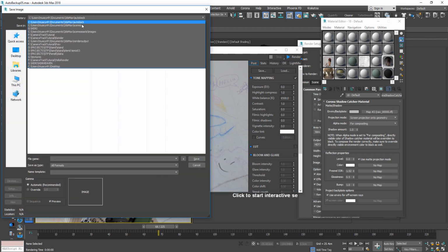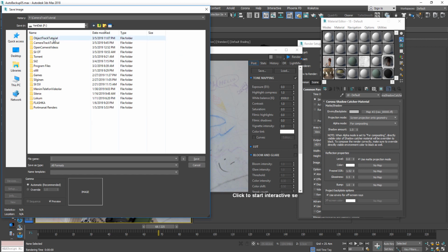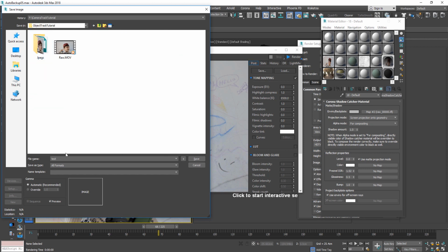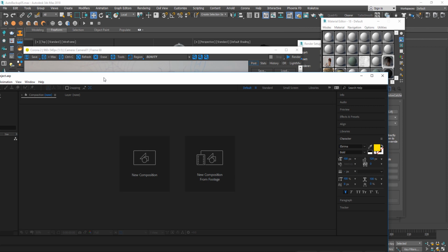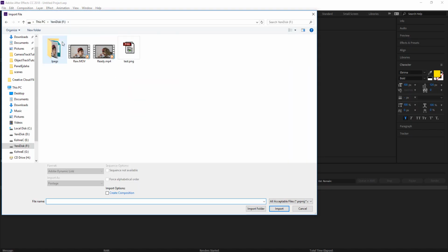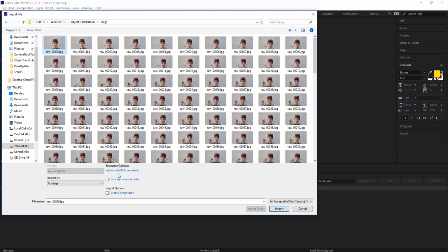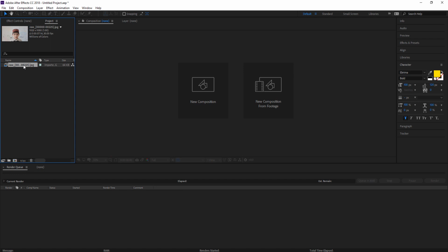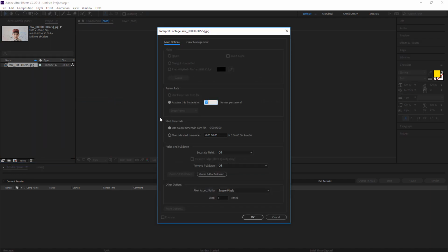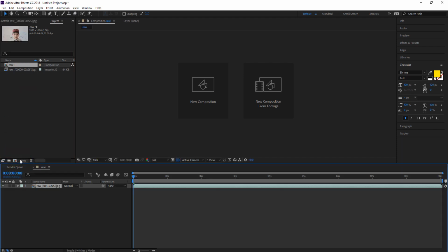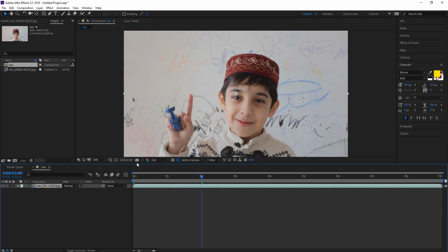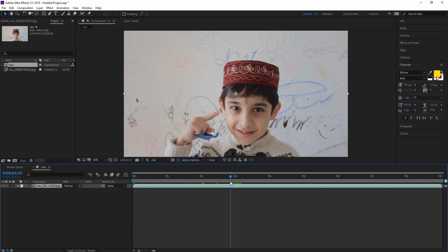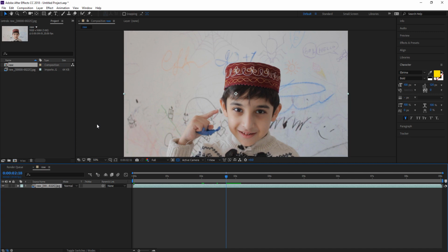Okay, my rendering I guess is done. So let's save it as a PNG file, and I'm at frame 68. So let's open it and import my JPEGs. Choose sequence and make sure your frame rate is 25, and frame 68 is gonna be 2 seconds, and 2 seconds will be 50 frames, so 2 seconds and 18 frames. This frame.